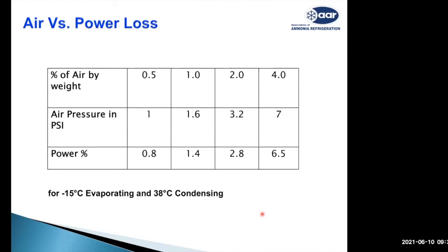If my compressor is open for servicing, the moment I open the compressor and remove those parts, air gets filled into that plant. When I put the compressor back, that whole air does not get removed. That air gets accumulated in the plant.